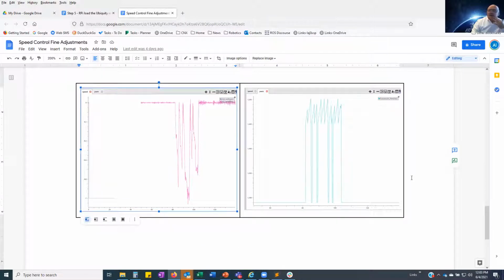Can you see my screen? Yes, I can. I know it's a little bit small. Ignore this graph, which starts down here at like 1290, which is a PWM signal going to the super servo on the transmission. So that's neutral for me. And 1500, which is basically this top line, is the max setting that I have it allowed to go.